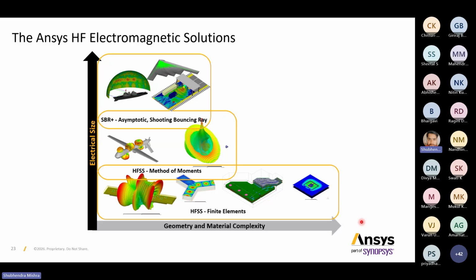Now, say I have analyzed one PCB. I have done the PCB-level EMI/EMC simulation for that PCB part. Now I want to move to the system level. For that, I need to place that PCB over the whole system, and for that, we will need the SBR+ solver.